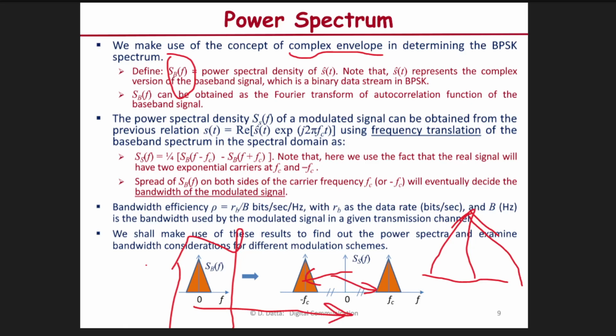So what you do is you take a shift of the signal by itself and generate the autocorrelation function. The autocorrelation function is always deterministic, it's not random. And it can be proved that if you take the Fourier transform of the autocorrelation function, you will get the power spectrum of the random signal. Right? So this is how you can find the power spectrum. You take the SBF, and from the SBF you find the spectrum of the modulated signal. So that is what I describe here.